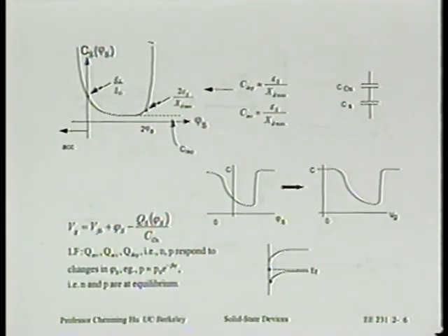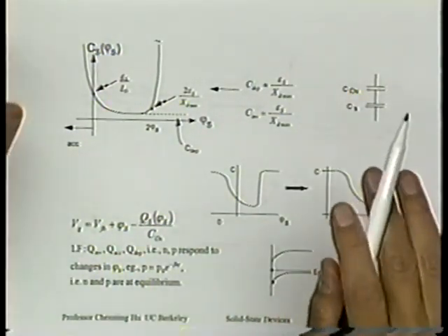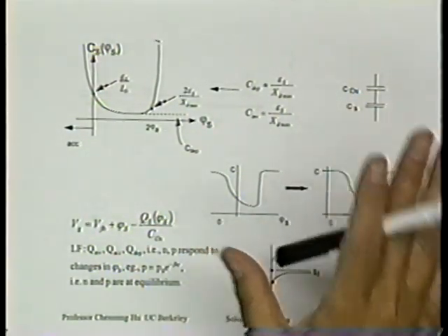Does that make sense? Right? If the inversion layer truly is 0, CS should be infinity. The reason it's not infinity, meaning inversion layer has finite thickness. Right? You will be able to get the average thickness based on this capacitance. Right? And that is the correct concept. It's physically not accurate. We'll tell you why, because this analysis did not consider quantum mechanics.